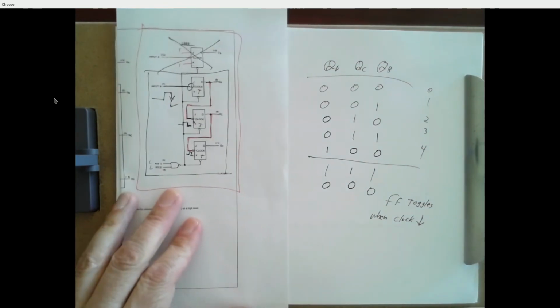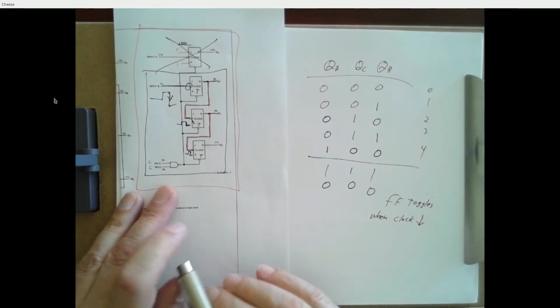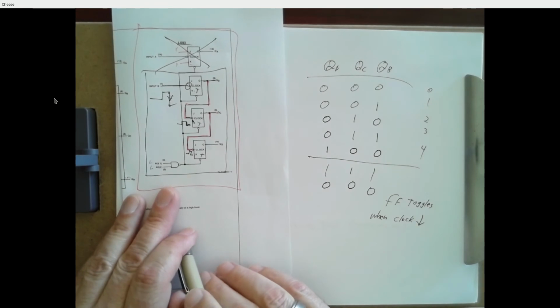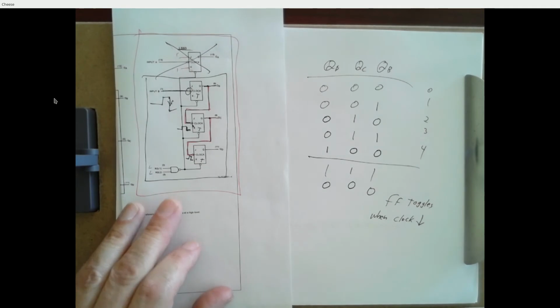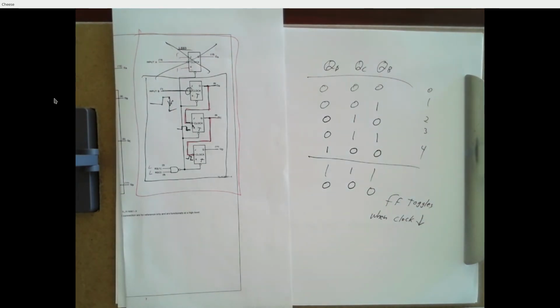And it works, but it's a poor design. If you remember why it's a poor design, I said something last week. I said a lot of things. Don't mess with the clock, right? That was the golden rule. All the clocks get fed from the same thing, and you don't monkey with that signal. The reason being because these state machines that we're analyzing and we're going to start building depend on the fact that everything happens in unison.